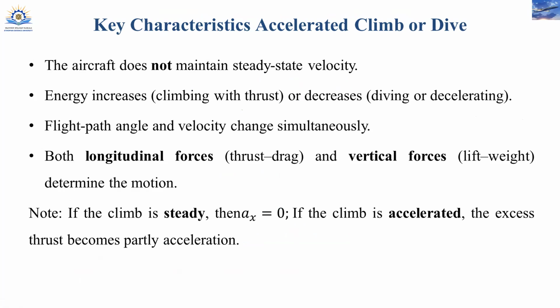So, what are the key characteristics of accelerated climb or dive? One is the aircraft does not maintain steady level flight. That is one of the parameters of steady climb or steady dive. Energy increases or decreases. When it is climbing, energy increases. And when it is diving, it decreases. The flight path angle and the velocity change simultaneously.